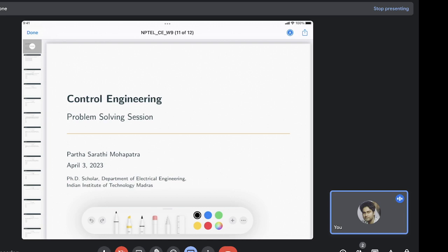In the lag compensator, because it provides a negative phase angle, it is called a lag compensator, and thus this phase plot is of no use to us, but the magnitude plot has a low pass filter nature. If you want a phase margin that is located, for example, in a very low frequency range, then we will use the lag compensator, and we will make use of its magnitude plot, not the phase contribution, because the phase contribution is a negative angle, so it will not give us benefit.